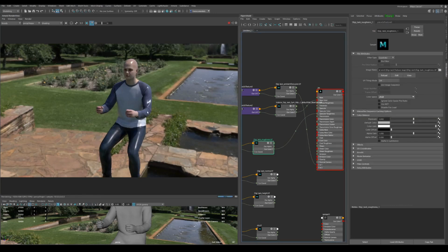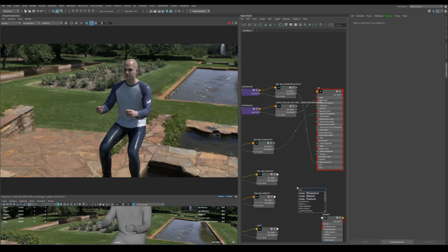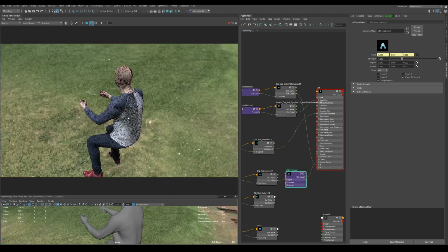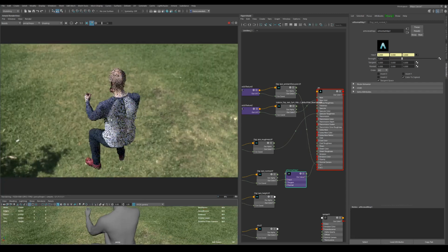Something that will help out with this shininess is applying a normal map and a height. So first let's connect the normal map. So after this is loaded, it should create some normal displacement on some of these highlight areas, and break it up a little bit. So we've got some less highlights here. So if you just go around a little bit, it's creating lots of issues here. So we might end up not using the normal map because we have a good displacement.